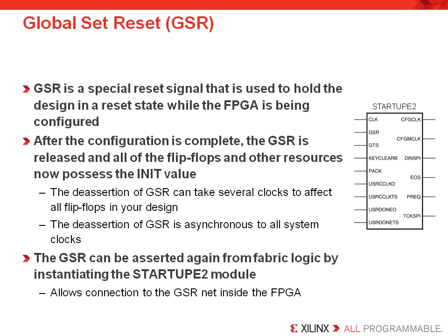The benefit, of course, is it does save you routing resources if you need a global reset, but you have to be aware you can't control which elements get set or reset when you drive a signal to the GSR port. All the elements get reset.